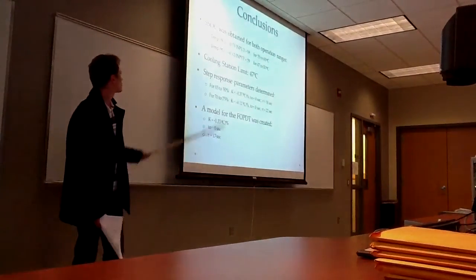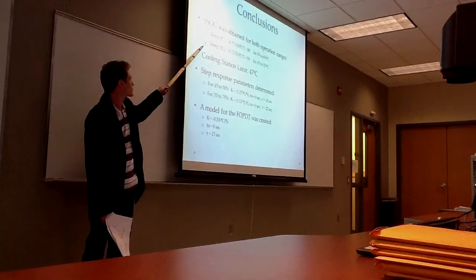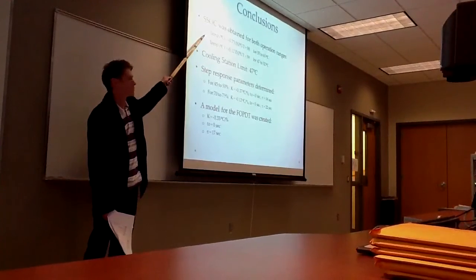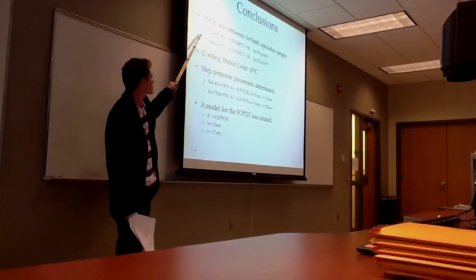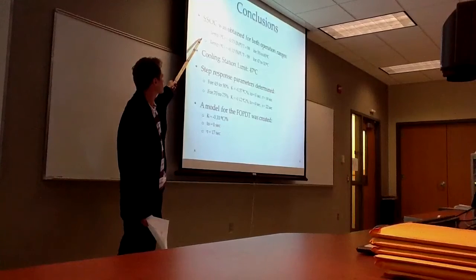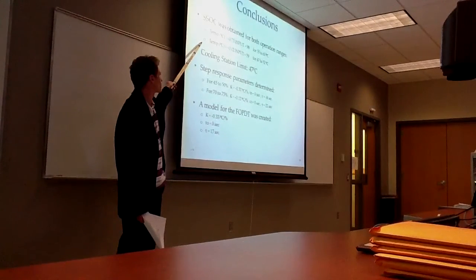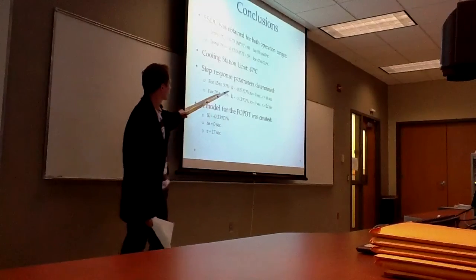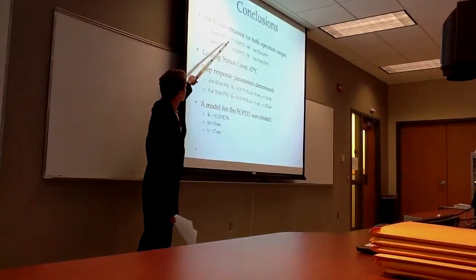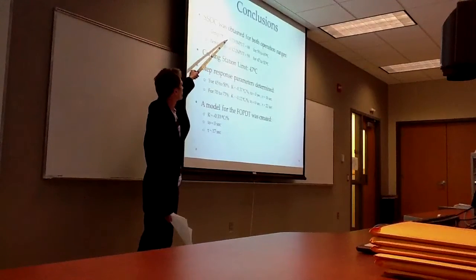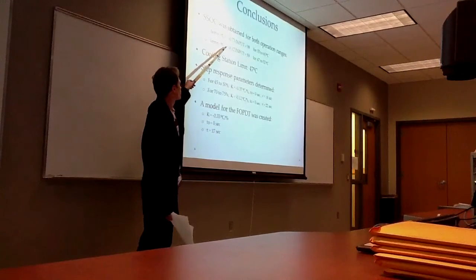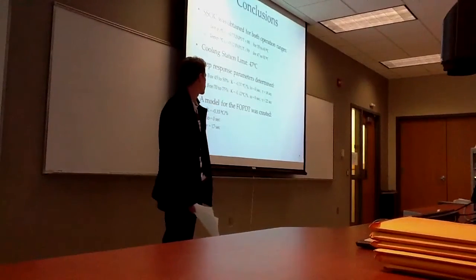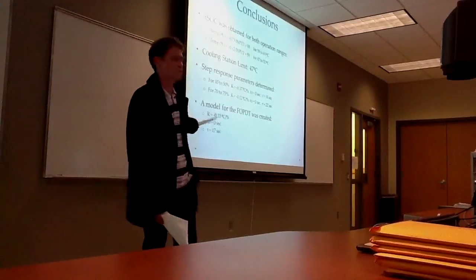And so just to repeat the results that I went through, we've got two steady-state operating equations. The first one is for 55 to 60, 65 degrees Celsius, and then the second one for 47 to 52. If you look here, this is the step response. The steady-state gain does not match up with the slope of this steady-state operating curve, but for the second range, the steady-state operating curve slope matches up with the steady-state gain. And then here are the parameters for the FOPDT model.